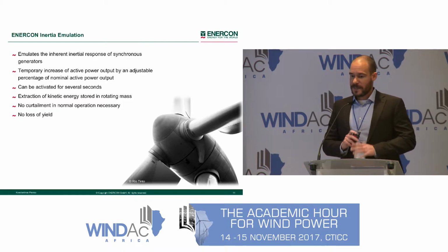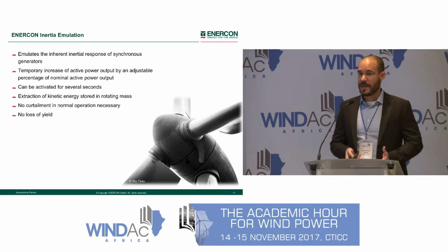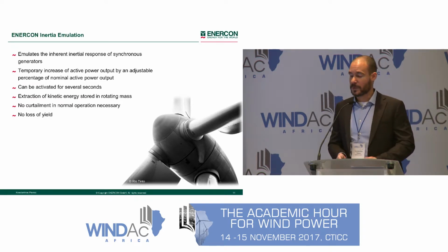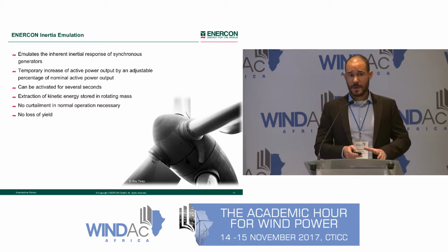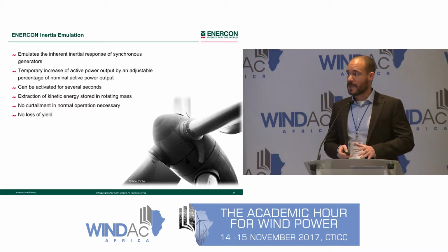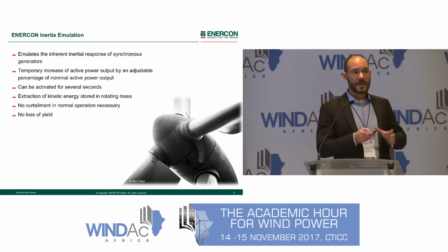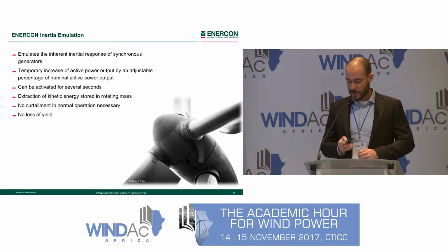This performance characteristic is a limitation of any wind turbine generator that is not curtailed prior to the event or is not supported by on-site storage. However, through elaborate algorithms, the active power output can nowadays be controlled in such a way that a smooth reacceleration back to its optimal point of the rotational speed can be achieved, as we will be seeing in a while.